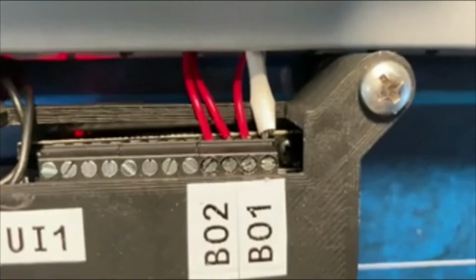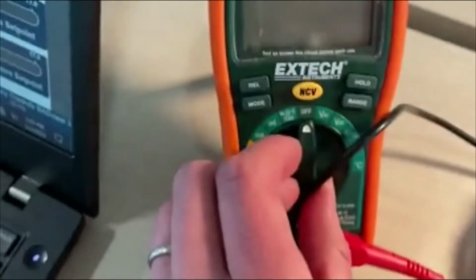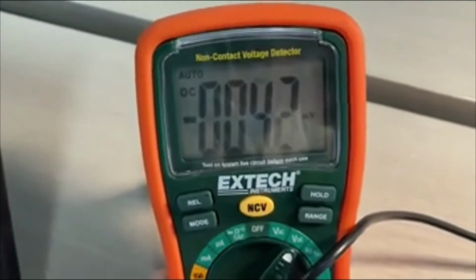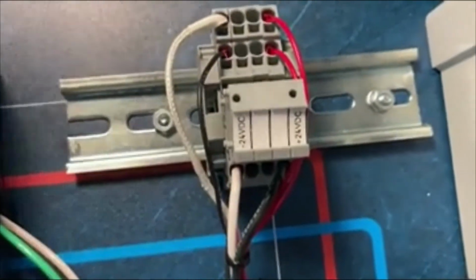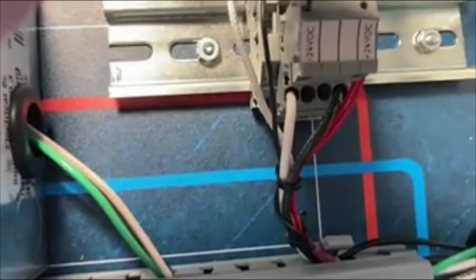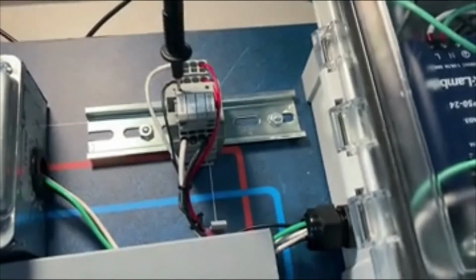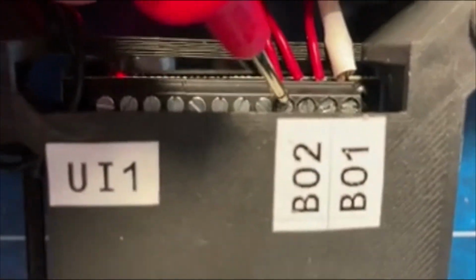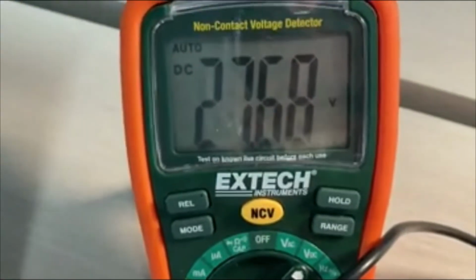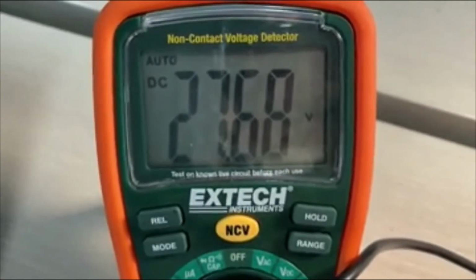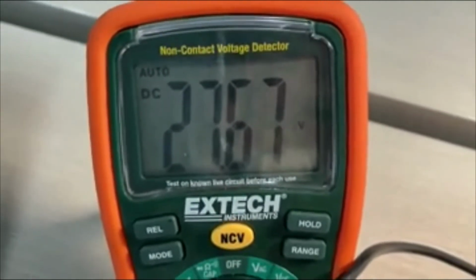So we can do this measurement of the fan relay by making sure our digital multimeter is set to measure volts in DC. So we can see it's on DC voltage, and we will begin by putting the negative probe into the negative 24 volts DC part of the terminal strip. So we can see that just stays there. And then we'll measure on the binary output side of the controller at terminal 4. And the digital multimeter is reading 27.68 volts DC. So that indicates there is 24 volts of power supply, even a little bit more than 24 volts is finding its way to that terminal.